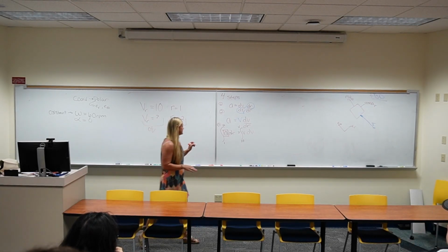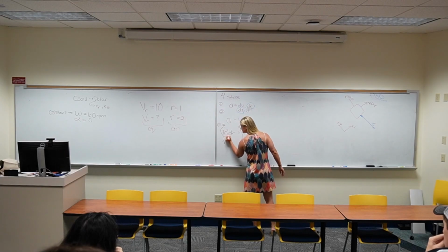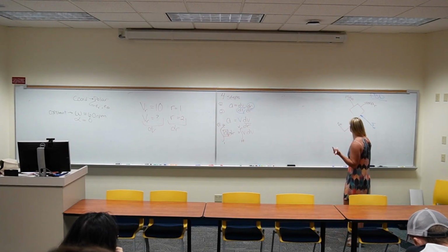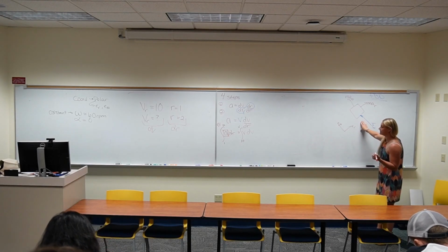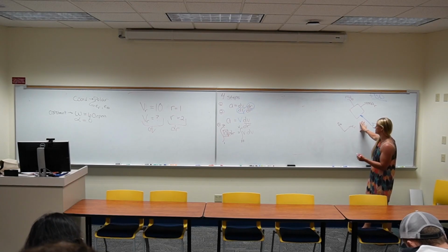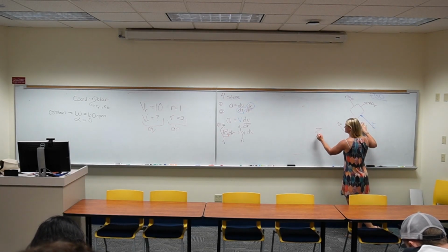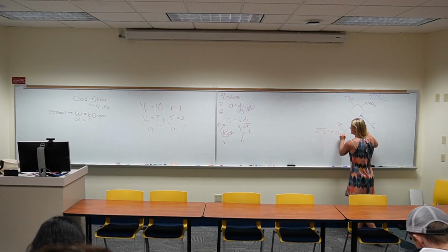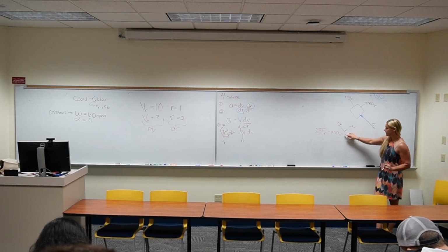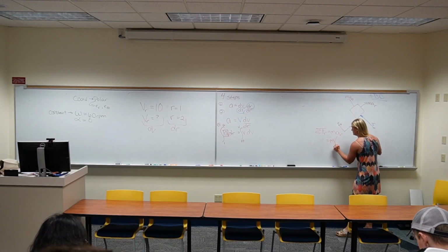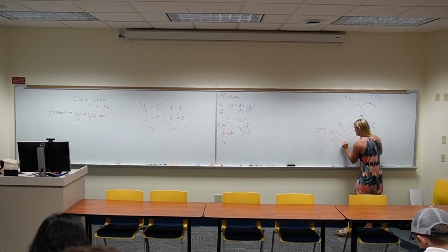So that means that this a is ar. Now we can go over here, and I can make my vector equation a scalar relation. The sum of the forces in the radial direction equals m ar. What is ar from your toolbox? It's r double dot minus r omega squared.